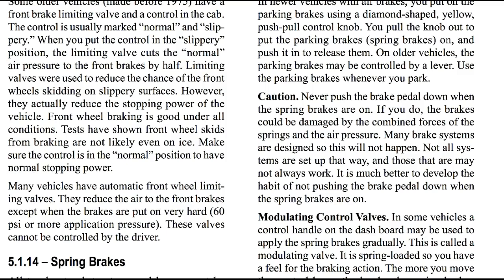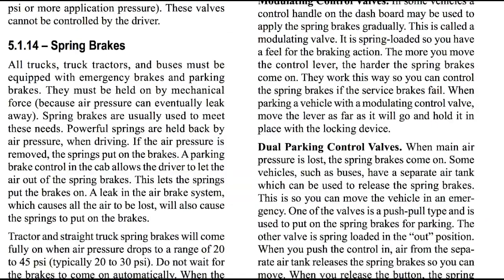Front wheel braking is good under all conditions. Tests have shown that front wheel skids from braking are not likely even on ice. Make sure the control is in the normal position to have normal stopping power. Many vehicles have automatic front wheel limiting valves. They reduce the air to the front brakes except when the brakes are put on very hard. These valves cannot be controlled by the driver.